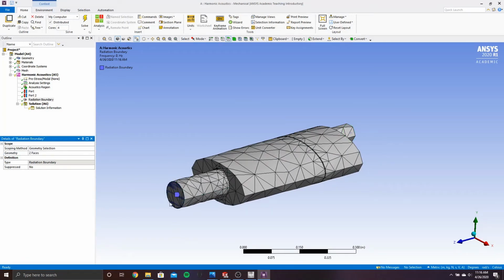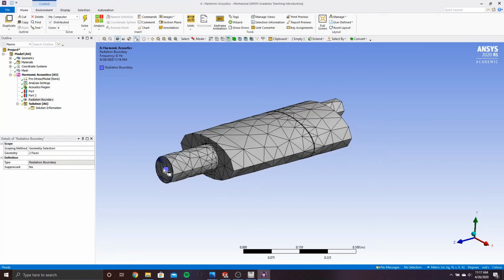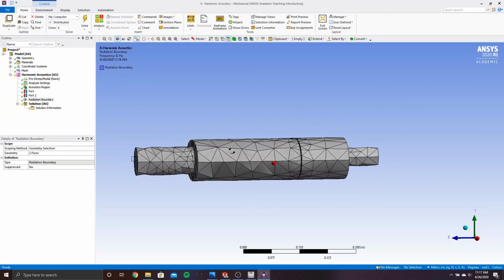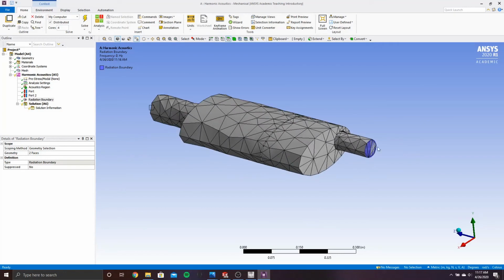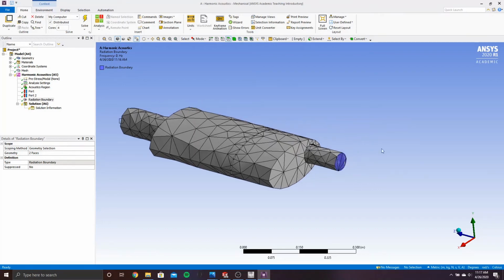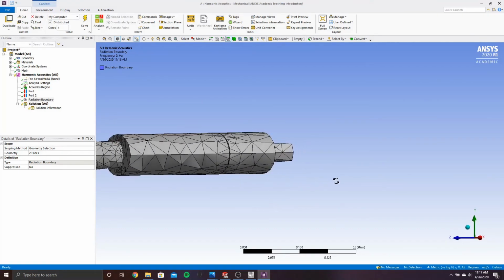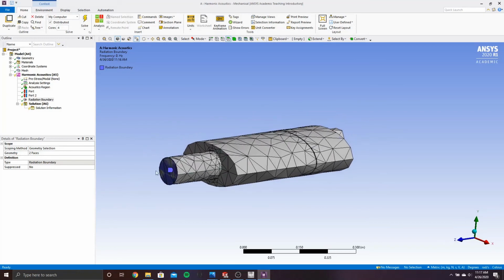So we have sectioned it there, and we're taking that same exhaust gas flow and putting it through. So we don't want anything reflecting off of this surface. The second side opens up to the atmosphere, so there'd be no logical reason why it should also be reflecting off this surface if it's just opening up into an essentially infinite body. This pretty much makes these surfaces like a black body. Nothing will reflect off of them in your analysis.